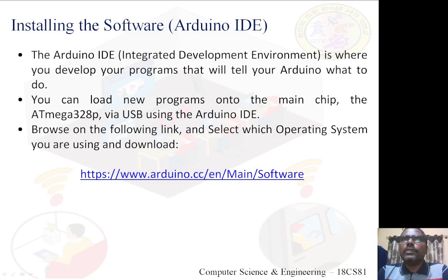So Arduino IDE is a software through which we develop programs that will instruct Arduino what to do. Now, after developing our programs using an Arduino IDE, this compiled program should be uploaded to the main chip, that is Atmega 328P. To upload, you should connect the Arduino controller to the computer using a USB cable.